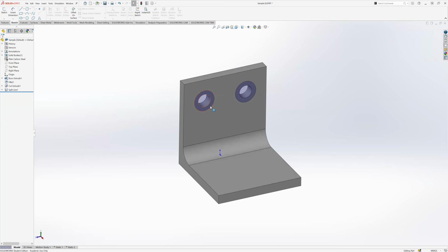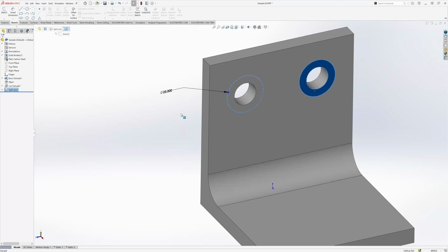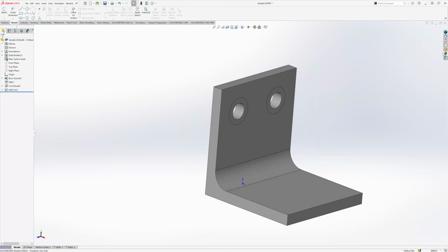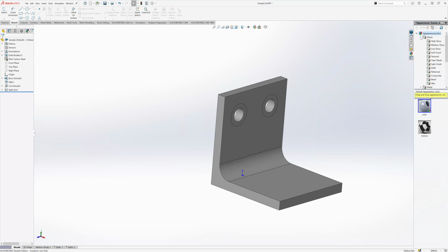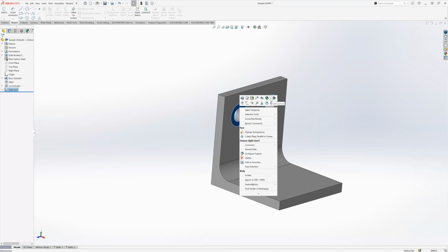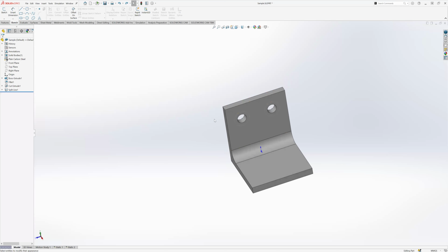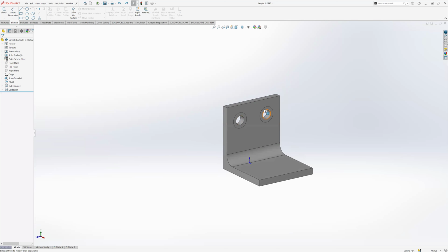And if you notice what has happened now is you've got several faces. You have a face here, and now you have these two faces here. So this is great if you want to put appearances on specific faces. If you have a logo, you want to go to appearances and maybe plastic, medium gloss or something. Maybe you want to put a red appearance. My thing is not actually showing up for putting appearances, but you can do an appearance on different faces here if you want to.